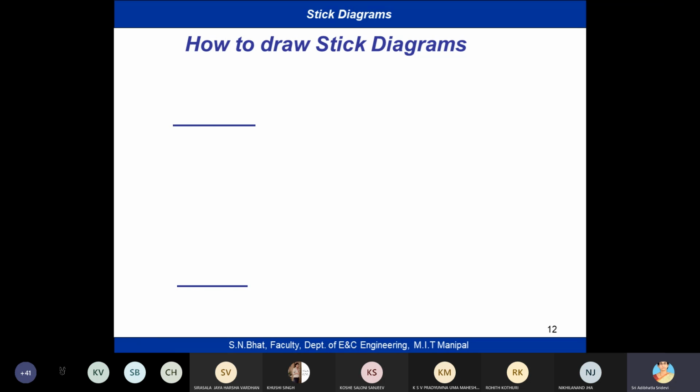First we start the stick diagram like how we draw the circuit. Generally, to draw the circuit, we have a supply line and ground line, or VDD line and VSS line. The supply line should be metallic, so the connection should be in metal. So we have a metal layer for VDD and VSS. First draw two metal layers.